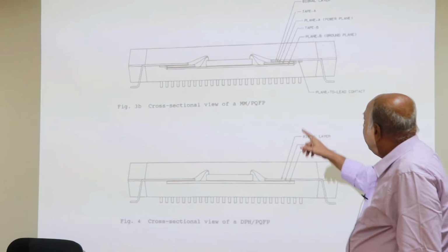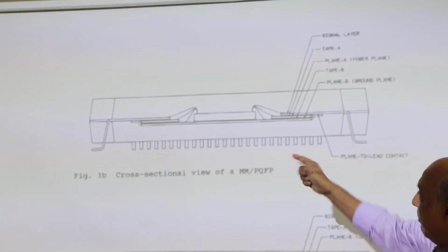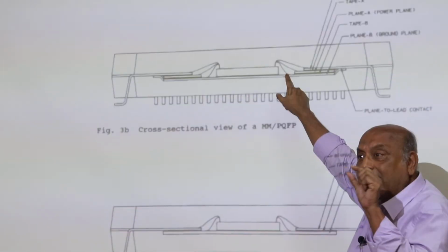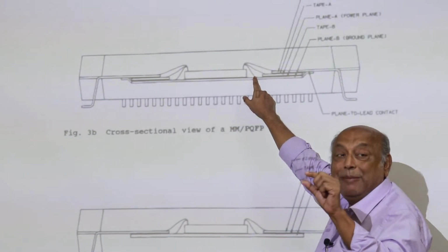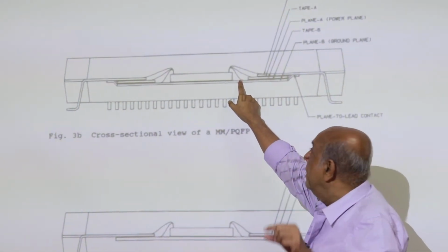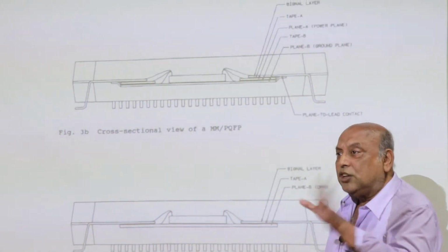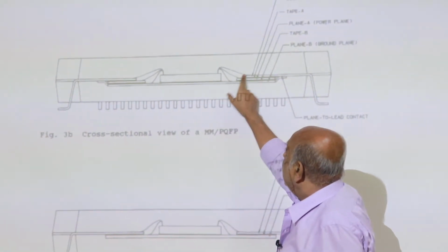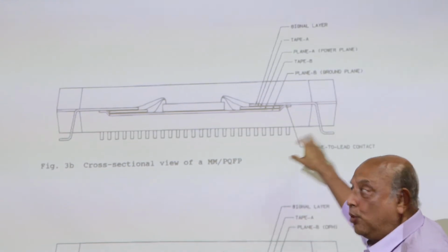Basically what I did, I have the silicon at the middle where you see the wire bonded. You see this bonding right here? This is very small, 5 mil, about 125 micron. Many of those make a square. So I keep bonding them down, and resistance is almost zero. This is another plane which is a little longer, and these are the leads that go out to the I/O. You see, they connect to the input output port.